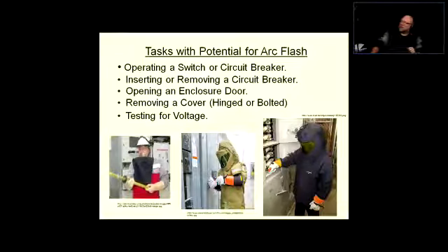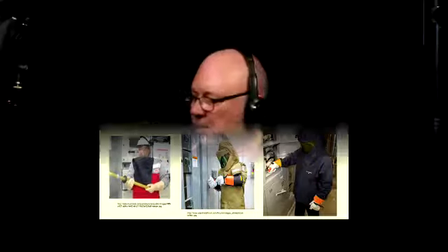Notice that the proper way of operating a circuit breaker on higher power is that you're not supposed to come to that circuit breaker and just flip it with your face right at it, right? There's a reason why the circuit breaker failed or tripped. If it was just some momentary failure or overload, everything is fine, probably nothing is going to happen. But if the fault still exists there, operating the circuit breaker can actually cause an arc flash.